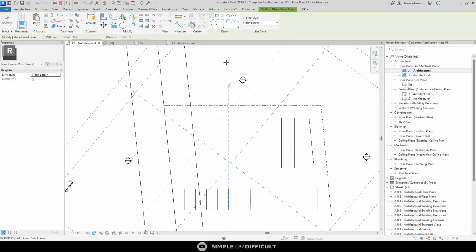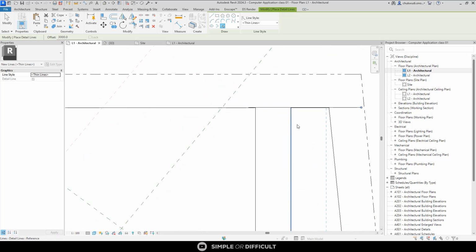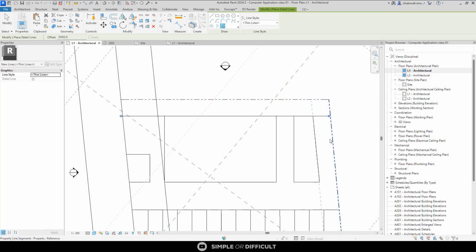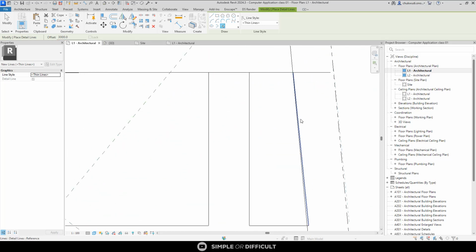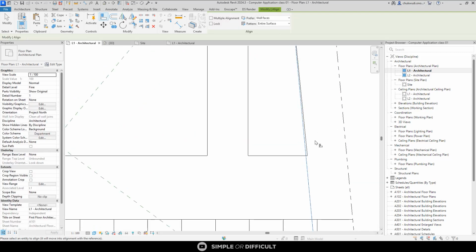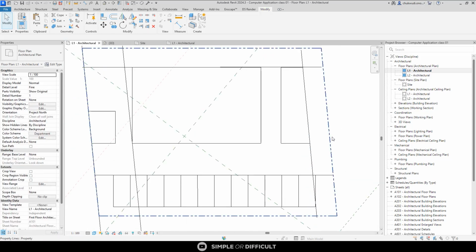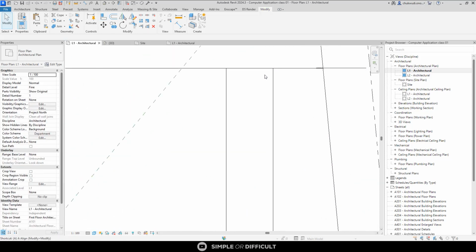So by the side, we're supposed to have 3 meters. This is according to the building code. Without this, your building might not get approved. Not that it will not get approved. You can see you have 3 meters from there. Also, we have 3 meters. Oh, okay, a little bit. We have 3 meters from here as well.